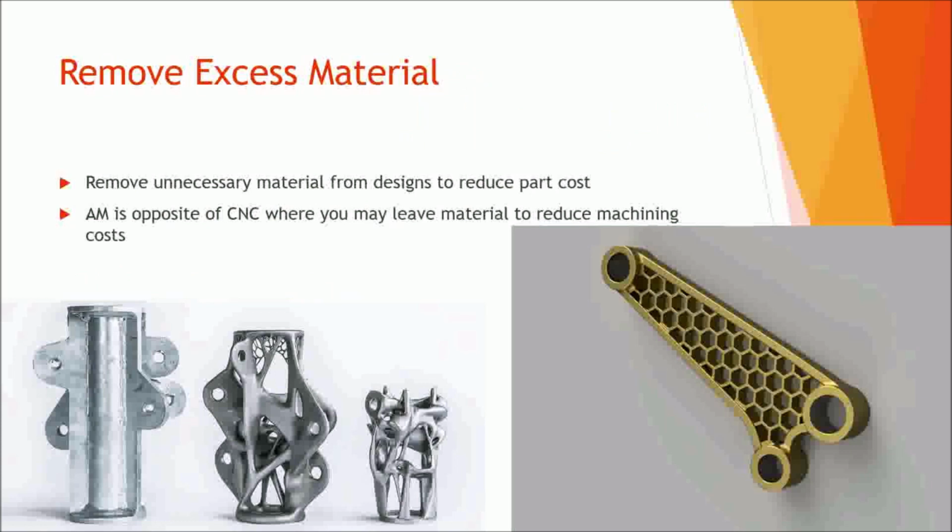Alright, probably touched on this before in the previous slide, but just to talk about it again, removing excess material. If you don't need the material there for one reason or another, get rid of it, because it's going to save you a lot of money and possibly print time as well.